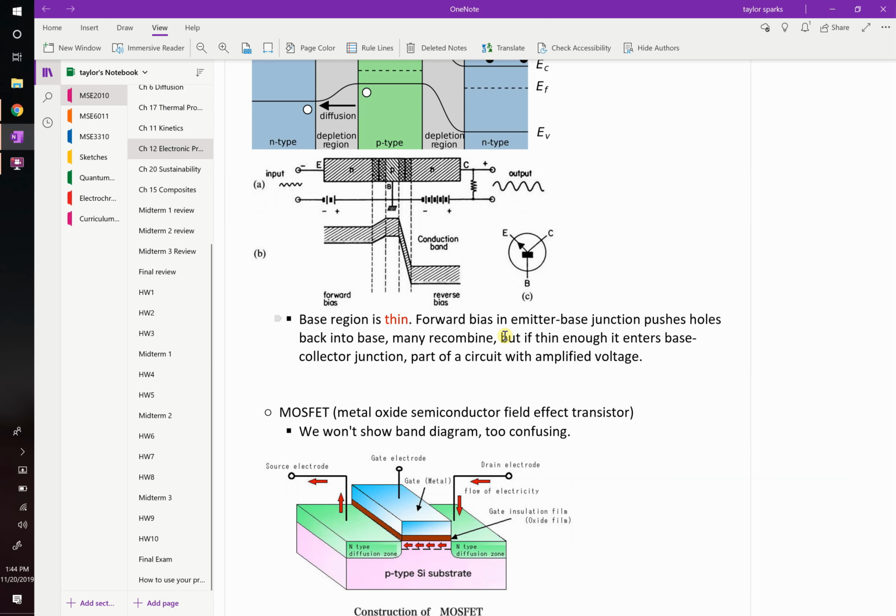But right now, if you move an electron from an N-type region into a P-type region, recombination will occur. No current will get through. But you can cheat. You can make this region temporarily N-type by applying a voltage across between your substrate and the top of your gate. We'll talk about how that works next class.